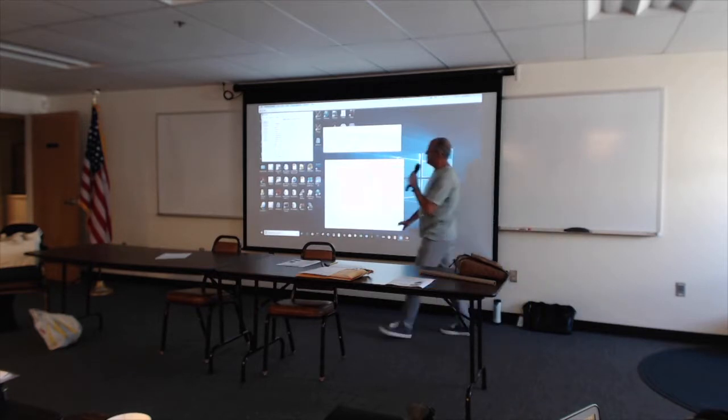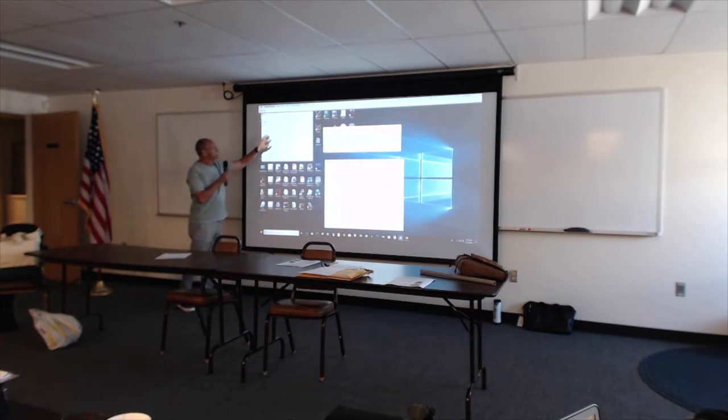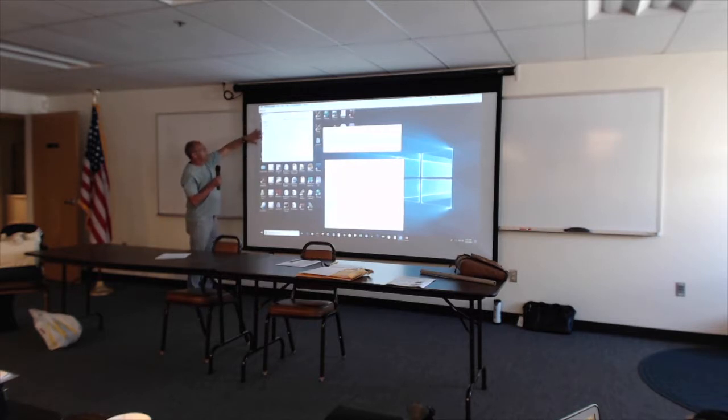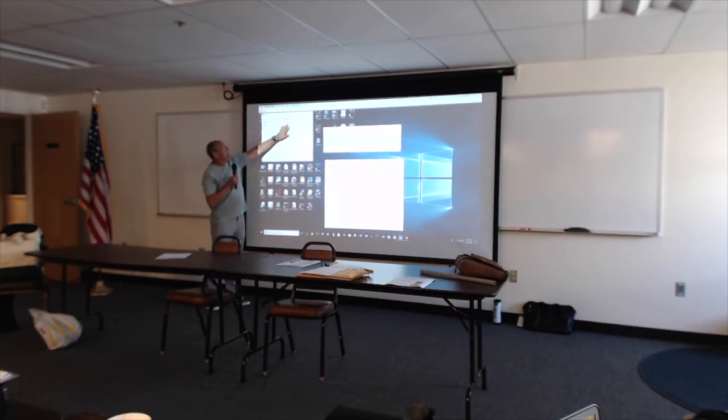But essentially, in this particular tool, you'll see that this area right here in the user interface is all your inputs into the design. The buttons here are going to be the outputs that you want to see from the results of the calculation. So we come in and one of the first things we do is specify the frequency range. I put the bottom of the 160 meter band here for the frequency. It automatically gave me a wavelength of 546 and some change, 546 feet for a full wavelength.